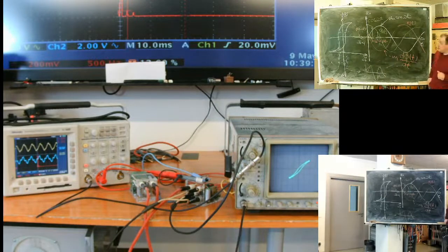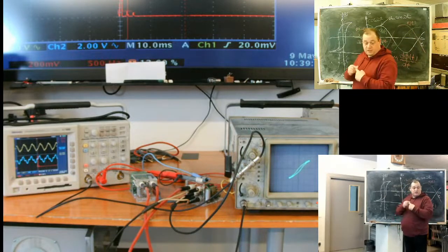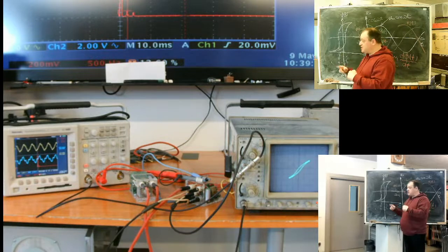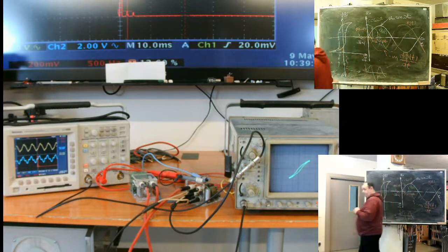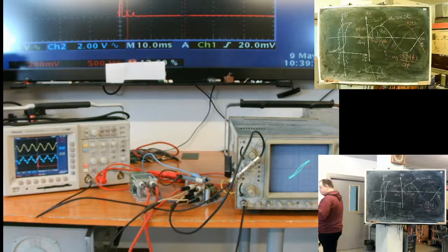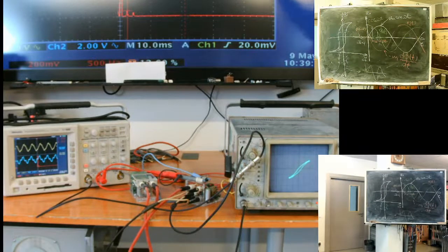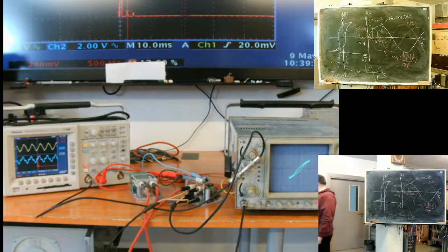Okay, so if we remove third harmonic from the flux, not remove but apply minus third harmonic to the flux, we will see distortions of the secondary voltage. And why we apply this inverted third harmonic? Because primary current does not contain third harmonic as it should be. Of course, it's a nice question. Why should someone apply this filter or do something like this? I did it for illustration.